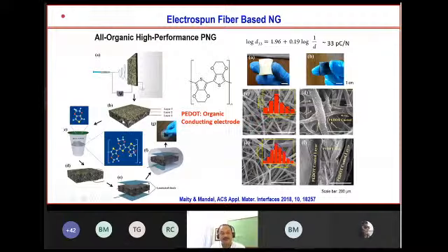Okay, so after vapor phase polymerization, you can see all the fibers are getting coated with the PEDOT. So we have PVDF in the middle, and then outside we have PVDF with PEDOT coating, and here also PVDF and PEDOT coating. So we have a 3-layer structure. The active layer is PVDF only, and the outer layer is the PEDOT coating.